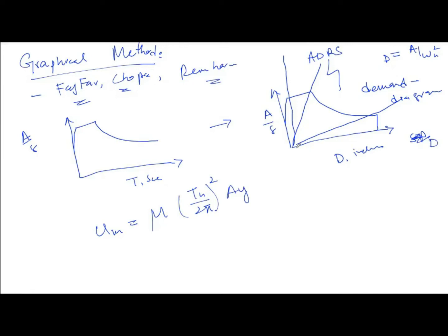So the results are represented in terms of A_y by g. For example, let's say if the yield strength of a system is equal to 0.225 W, in terms of the base shear coefficient A_y by g, it will be shown as 0.225.